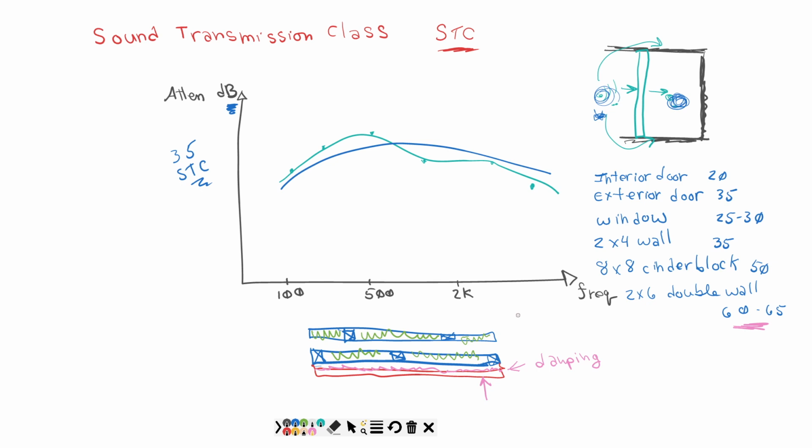So it's the same thing with sound. This thing has to be really solid. All the gaps. That's why I said the joints on the drywall, you want to overlap those. You do something like this, and like I said, you're going to have really, really good sound isolation. Not soundproof, but it is excellent sound isolation. All right. Okay, so that's how we sort of prevent sound, or how we can quantify how well sound is